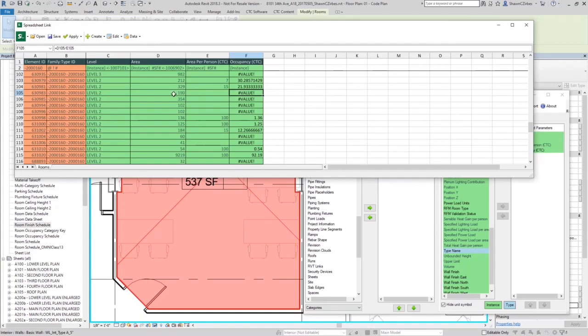That's because Excel or spreadsheets don't like dividing a value by nothing. Divide by 0 is a horrible thing. It doesn't like that. And so it's giving me errors here. I have to handle that somehow. And I'm also getting decimal points of people, and I like to round to the nearest whole person. So I'm going to go ahead and do that now. I'm going to write a little formula here. If error, do some things, and then do some rounding to, actually, let's do round up to 0 decimal places. And if there is an error, put nothing. So I can run that down, and it auto-fills that down for me and takes care of all the maths, handles the blank cells here, does all the work. And I'm basically done. I could apply this directly back to my project and have my occupancy filled out.